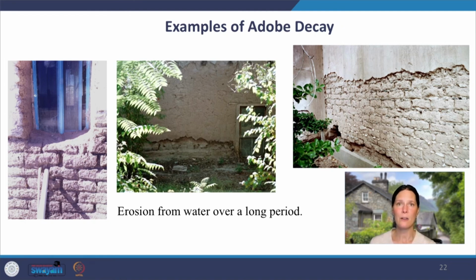By the time the stucco shows problems, big cracks, areas detaching from the wall or falling off, spalling, there is much deeper damage beneath. So the relationship of clay bricks to clay or lime plaster is critical.